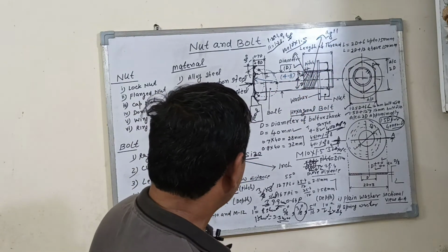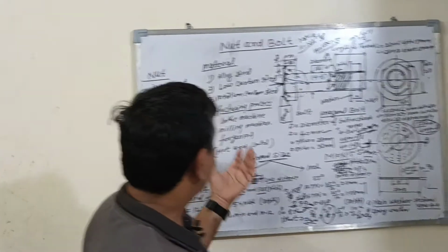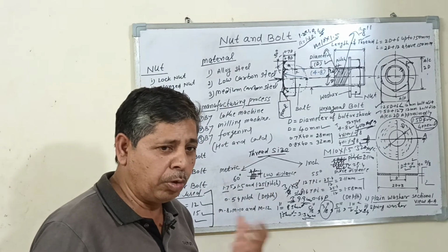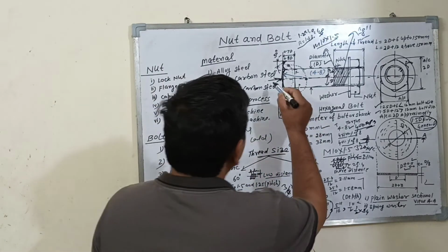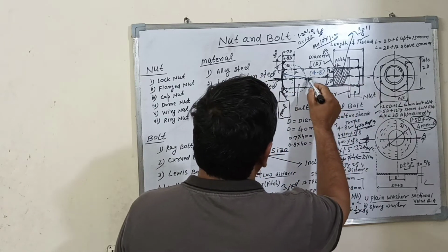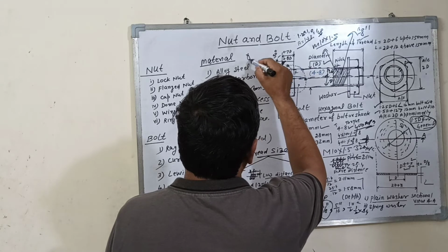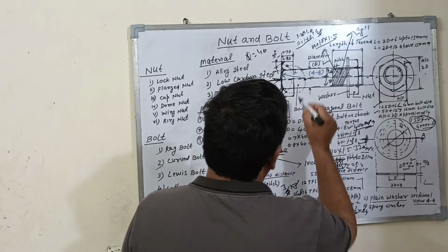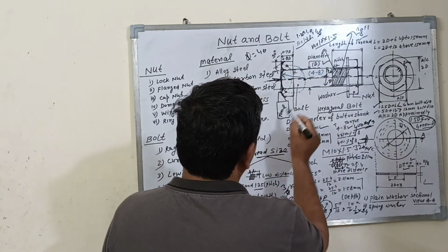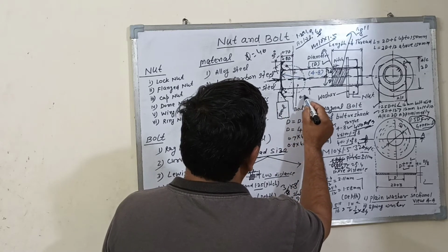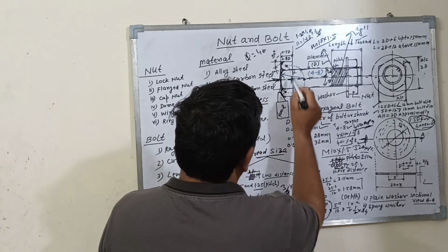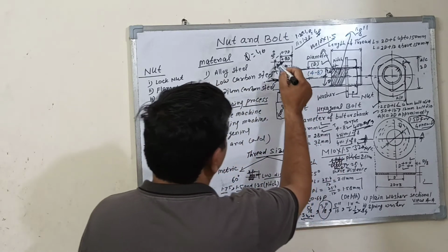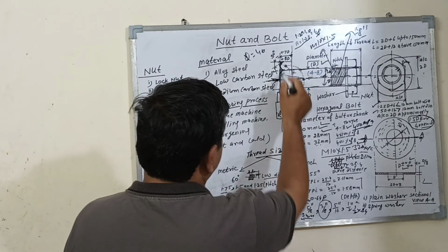So this is how to draw the bolt on a drawing sheet. You can draw a center line, and here is 20. If the diameter is 40, 20 is the line here, 20 equal to 20. A perpendicular line is here. Then from this side, 0.7d, so you can calculate with this formula. You can take this dimension 28 or 32. Draw a line like this.